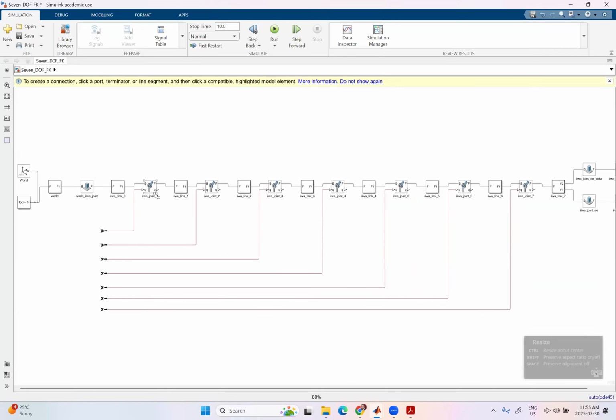Also, we are providing or reading encoder data of each one of these joint placements. So obviously there are encoders coupled to the joints, so we would want to export them. We need to use a block that is the reverse of Simulink converter to basically this Simscape simulation environment. For that, I would do the reverse. So I would say PS to Simulink converter.